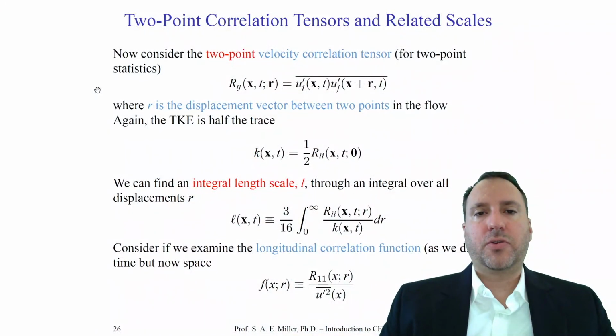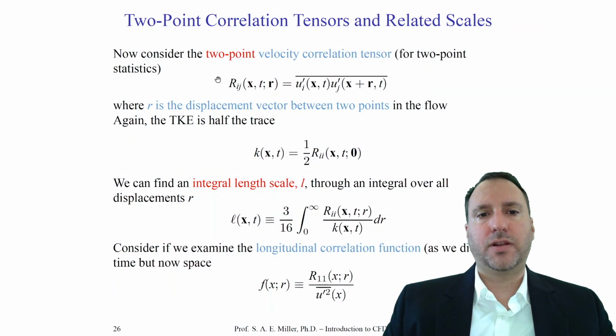Now, we've shown one-point statistics to find a very important time scale called the Taylor microscale. We still need to go towards our closure problem, which is the whole subject of all kinds of different turbulence models, which are implemented in CFD codes and what you're actually evaluating in this class and others. Let's now consider a two-point correlation of velocities. So once again, we have our two-point correlation.